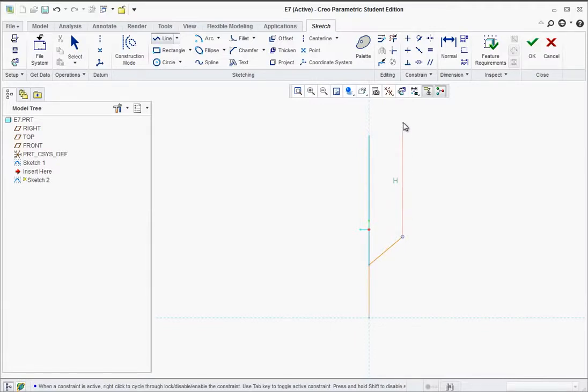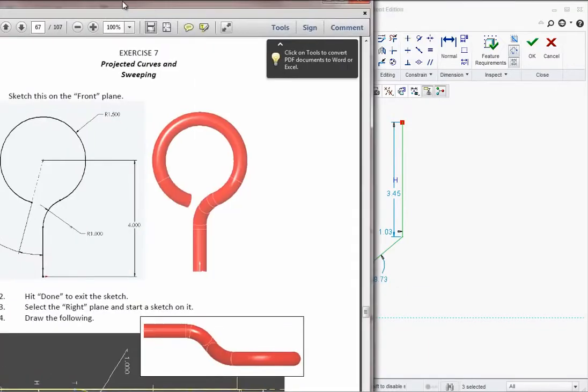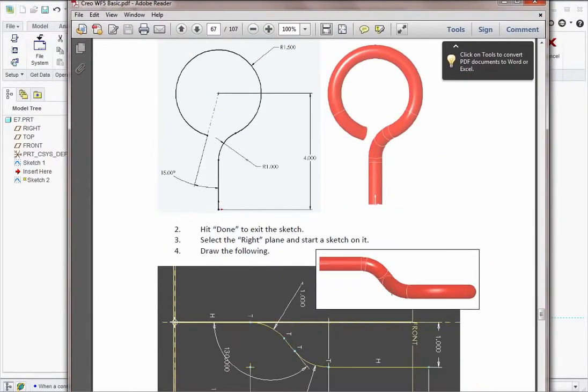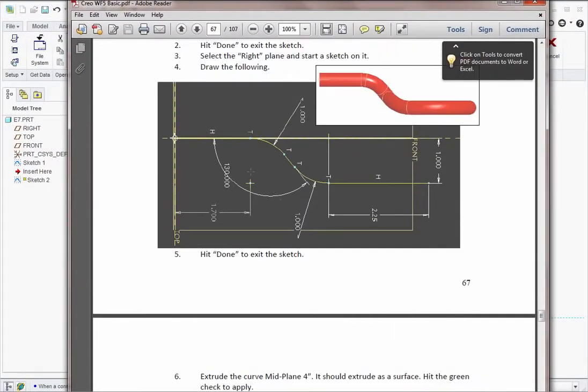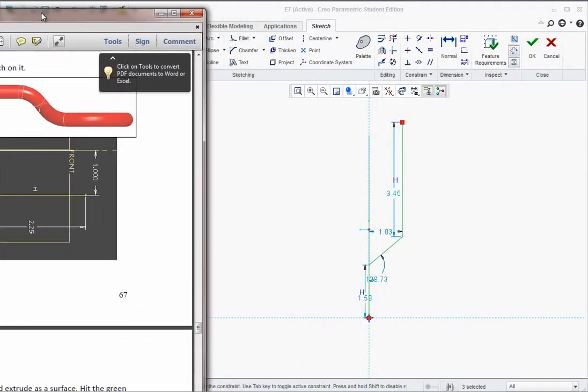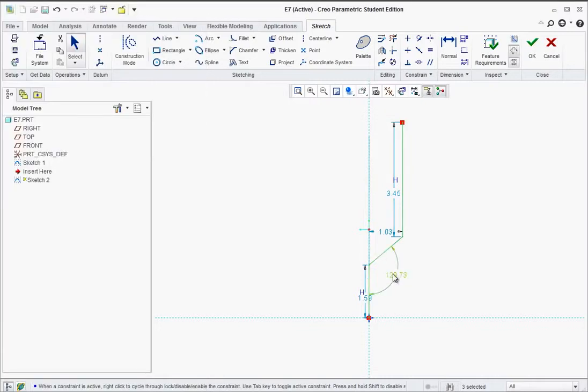We'll dimension it, so if you're not exact, don't worry about it. Click here. That's supposed to be horizontal. Okay, and so we get some of the dimensions here, and you can see in the book here, we are now on this section here. So we're going to go ahead and put in some of these different dimensions, like 130 degrees, this dimension. If you don't get this dimension, remember you can click on the normal dimension. Just to show you, you can click on this line and this line, then middle click, and it will override whatever dimensions there. So it's supposed to be 130.